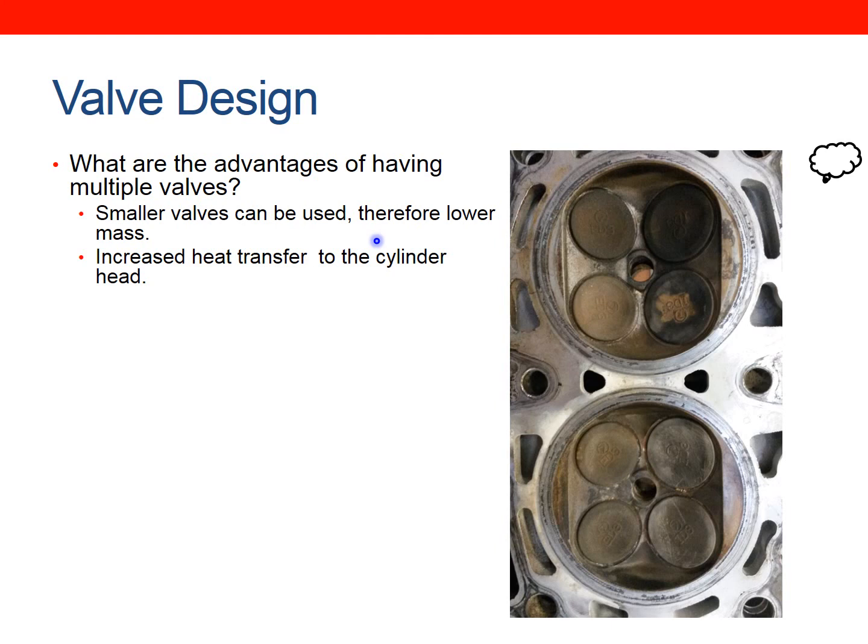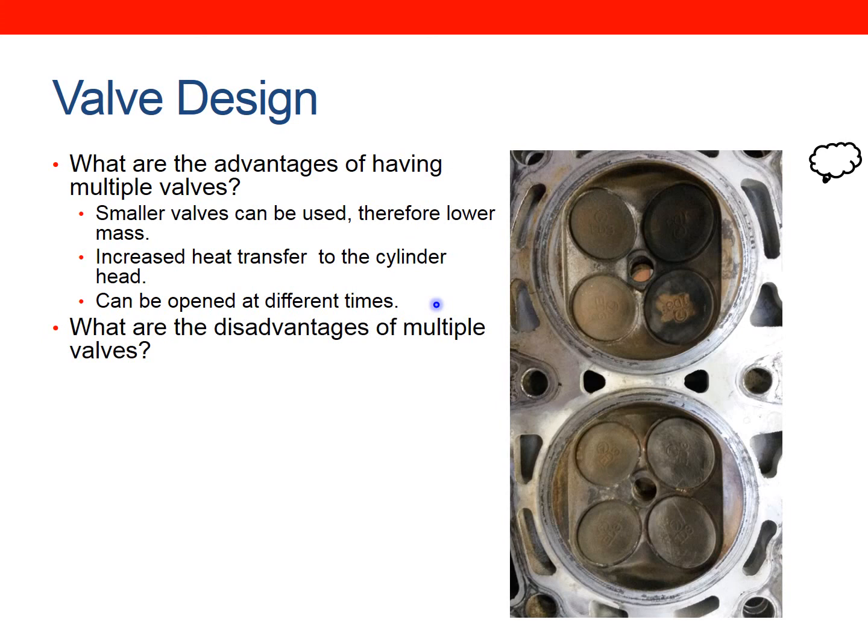You can also have increased heat transfer to the cylinder. These valves also play an important job. They are transferring the heat that's being convected onto them through the valve seat into the cylinder head and into the coolant. There's no cooling on the valves, so it's important in terms of heat transfer as well. And it also gives you an advantage in terms of the engine design. If you open your valves at different times, depending on how well you design it, you can create all kinds of different flow regimes within the cylinder, which is going to increase turbulence and increase your mixing. However, as with any engineering problem, there are some disadvantages.